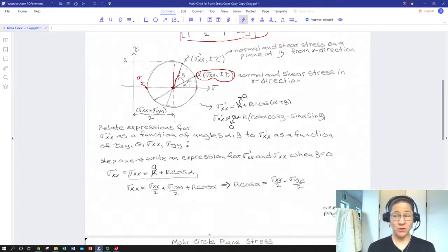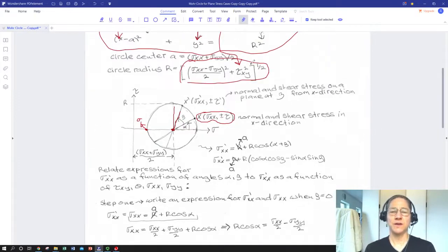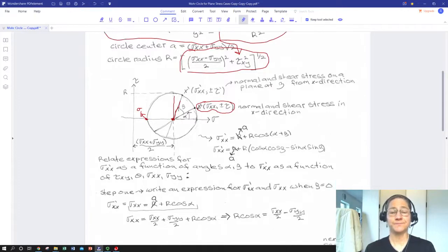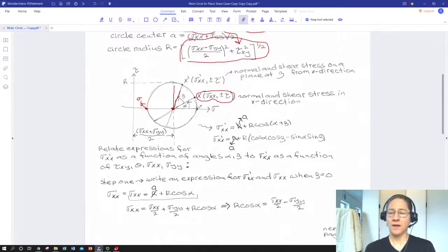As soon as you plot that Mohr circle, you can immediately see, oh my goodness, my externally applied stress may be up here, but if I have a large radius to my Mohr circle, say because I applied a lot of shear stress, I may have some angle in that body somewhere that's experiencing a lot more tensile stress than I applied in the x direction. That would be really valuable to know, and all you have to do is plot the circle to see that.